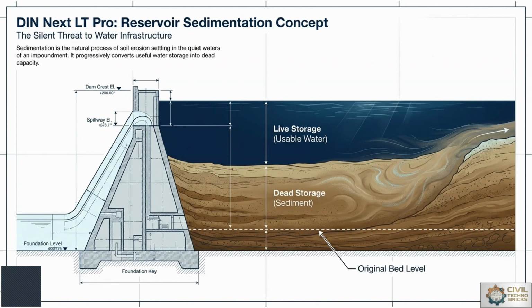By comparing historical images with current data, we can see where the reservoir is becoming shallower, or where a large amount of sediment has accumulated. This remote sensing monitoring is significantly cheaper than physical dredging or underwater sonar surveys for large-scale reservoirs.